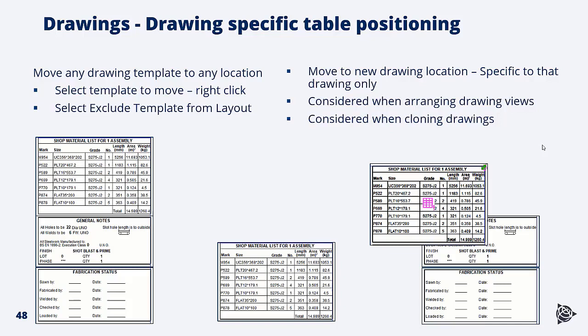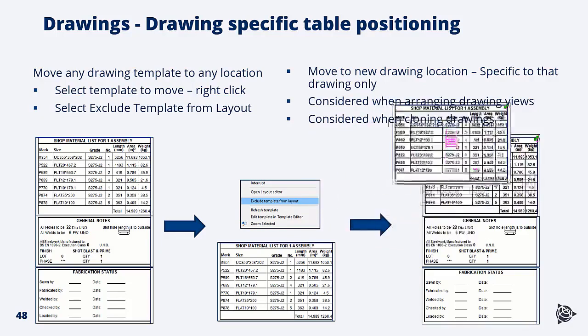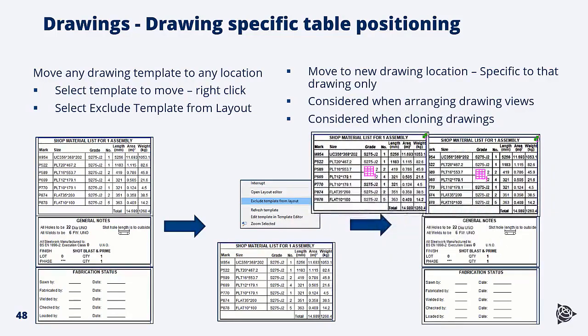This is great for expert users who want to simply rearrange a drawing quickly, or for new users who want to create a drawing of a particular style. It's considered when arranging drawing views, and it's also considered when cloning drawings. However, it's specific to that particular drawing that you have edited. So you can see here, click on the template to move, exclude from layout, and move it to any location on the drawing that you require.